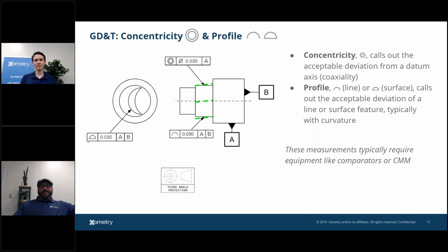And then we get a report out from the CMM that says it's good or it's not good for the whole part. And then there's no real dimensional callout. So if something's out of that profile tolerance, we have to go back and figure out what's out. Is the whole position off in X a thou out of tolerance? Is that what's throwing that profile out? It creates a nightmare.